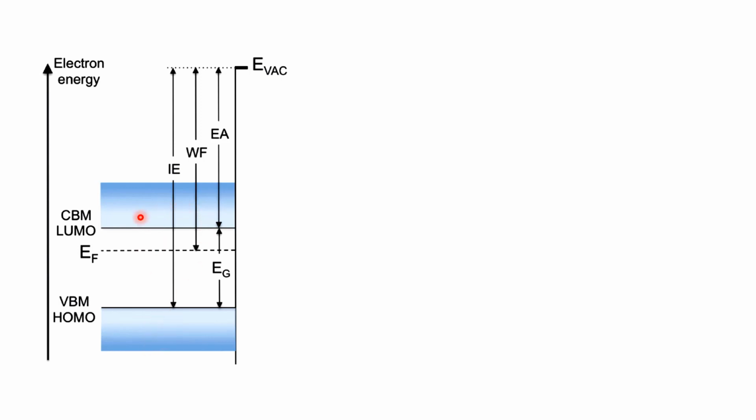For usual materials like metals, insulators, and semiconductors, we define them with a valence band maximum and conduction band minimum. But in the case of discrete materials, instead of energy bands they have energy levels, called the highest occupied molecular orbital and lowest unoccupied molecular orbital. In between the valence band maximum and conduction band minimum, we have the Fermi level.